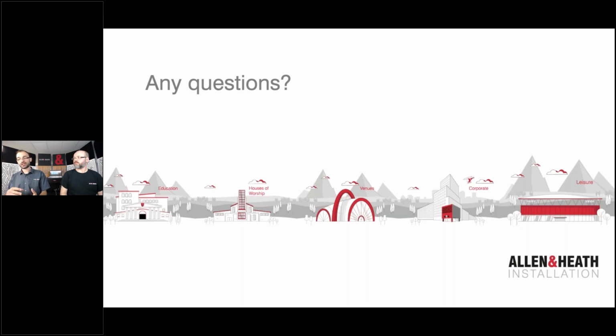For example, you can recall different scenes in the dLive system. And the purpose of those scenes might be simply to change the GPIO messages or contacts on an output to, for example, switch on a projector. If you're familiar with the dLive, you will know that you can filter anything else out of that scene. So that scene will only effectively switch on the projector, and with a button in custom control, I can do just that. So there are multiple ways of interacting with third-party devices.